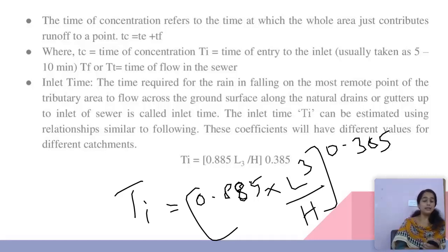We can calculate this inlet time using this equation, and the time of flow. The time of entry to the inlet can be taken as 5 to 10 minutes. Then adding these two, we will get the time of concentration.